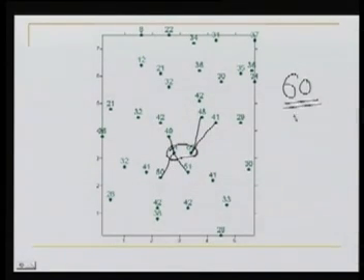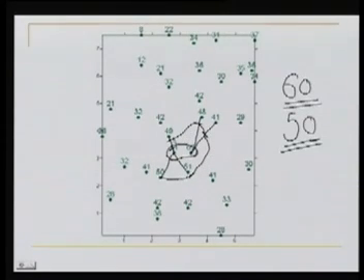Next, if we are interested in a contour of 50 meter, well, where it could be? If this point is 61, this is 49, 50 will be here. Again, this is 48, this is 62, 50 will be here. Then, in between these two, because this is 41, 62. Over here, the point is 51. This is 41. So, our contour should pass here. Then this point is 50 itself. So, our contour should look like this, and finally it joins here. So, that will become the contour of 50.